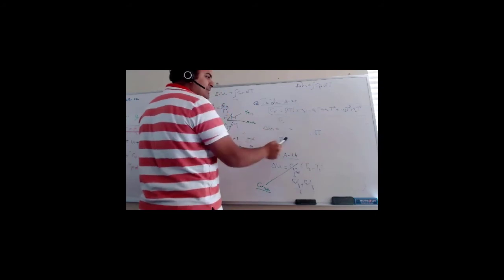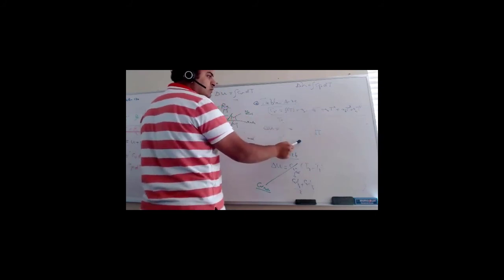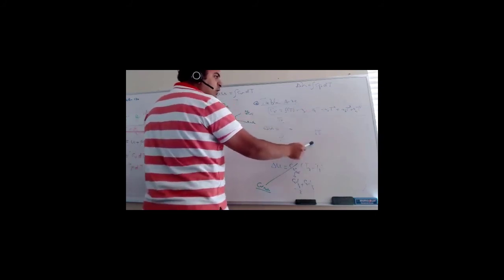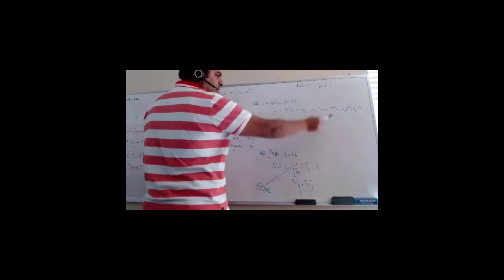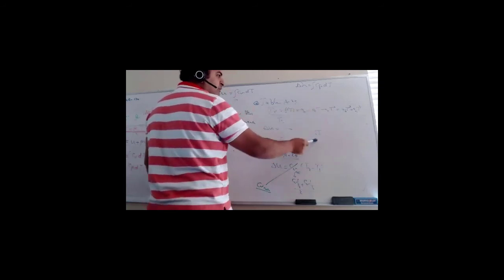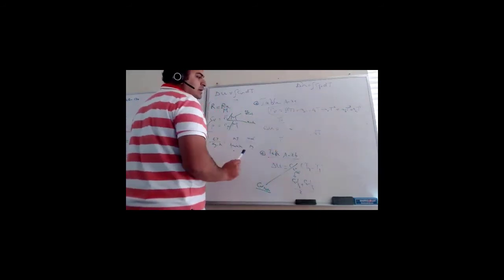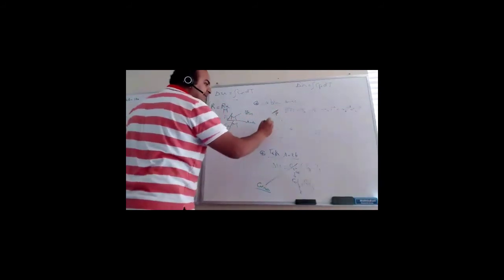It will be B0 T plus B1 T square over 2 plus B2 T cube over 3 plus B3 T power 4 over 4, and so on. Substitute by upper limit minus lower limit. You get exactly delta H. So you can repeat everything for CP, delta H, and so on. Make sense? Does anyone have any question?